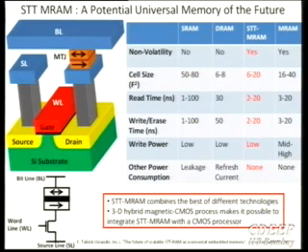So in MRAMs, you don't use spin torque current to change the magnetization of one of the free layers. What you do is you have an external field, and this external field is applied to change the magnetization. Unfortunately, if you have an external field, one can show that concentrating that magnetic field is very difficult. You need some coils, and maybe you have to introduce some high permeability material inside, and so on. All those different things that you have to do become very difficult. So from the scalability point of view, if you have a nanomagnet, one can show that spin torque is better. In fact, very recently, and this is a reality today, I think it is Sony who fabricated this kind of device and a memory structure.